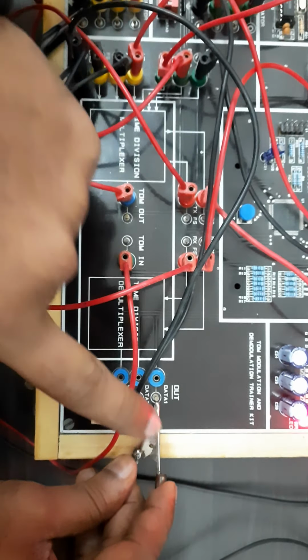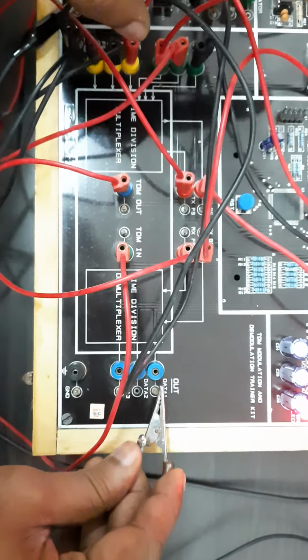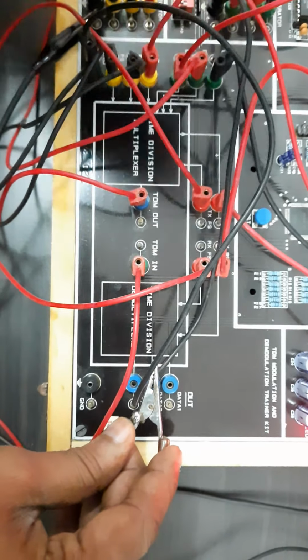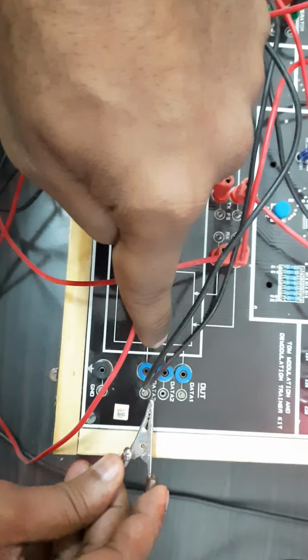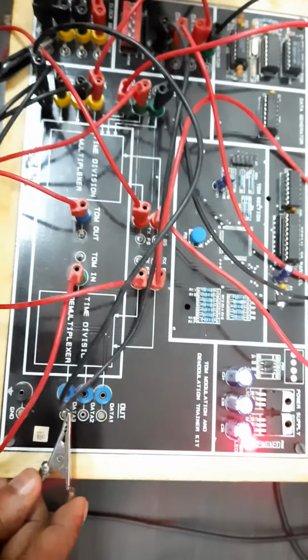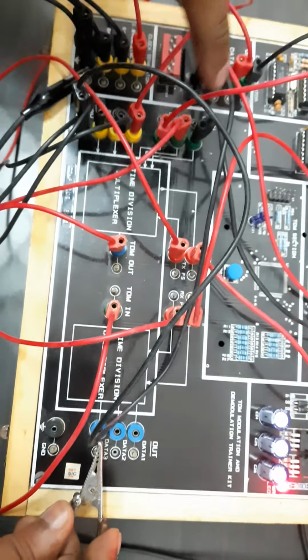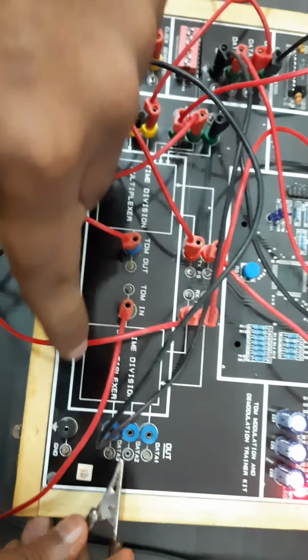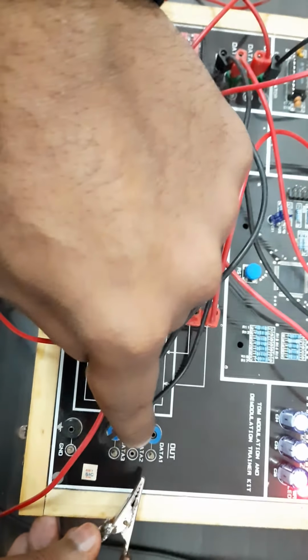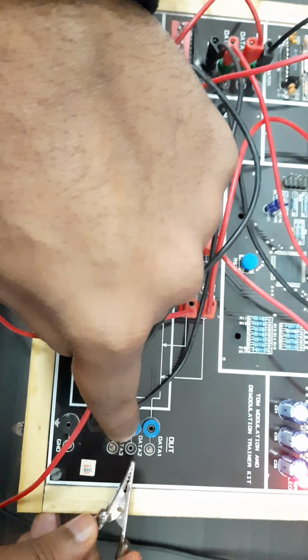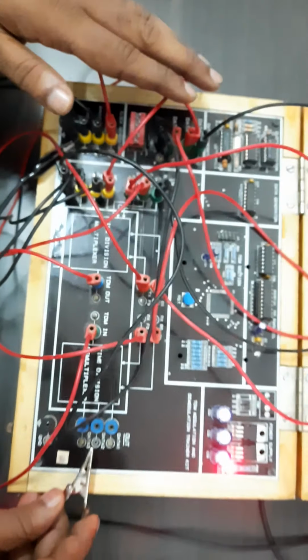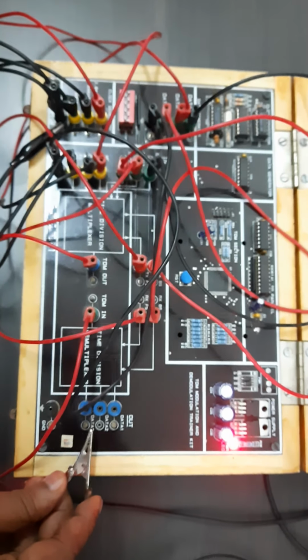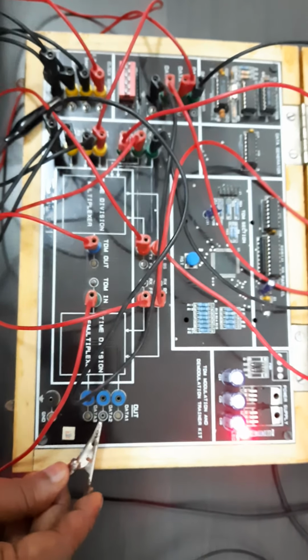Again we need to get the output at these three. Whatever information we have sent here from the data generator, these three inputs, has to appear at the end. So we need to observe the waveform at data 1, data 2, data 3, these three graphs, the TDM output, and the TDM demultiplexed output here. These are the original data which appear at the receiver section, right? We'll share the theoretical background of this experiment in the form of text, this is how the TDM experiment is done.